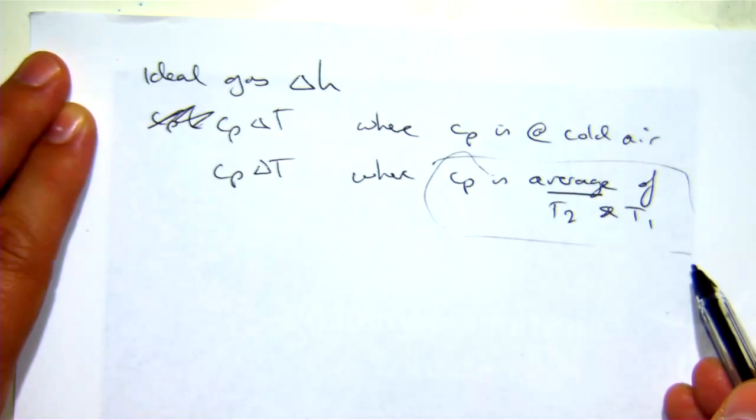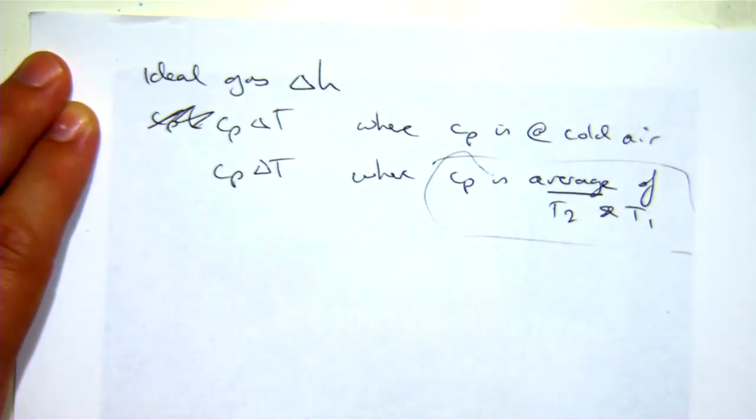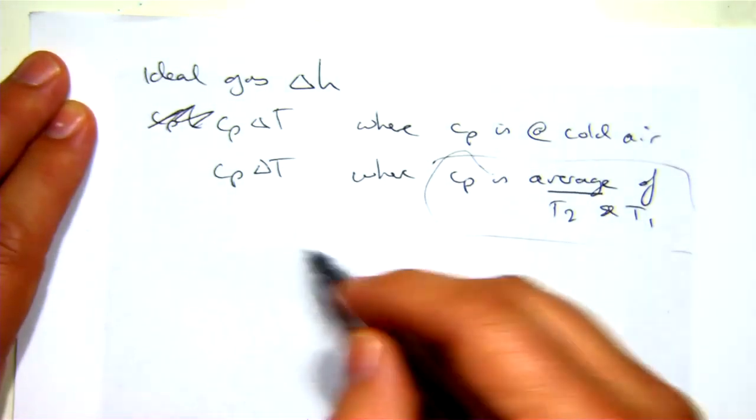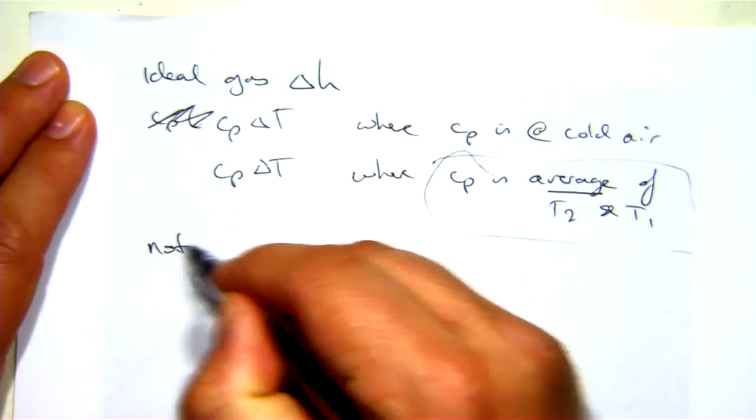So that becomes an iterative process that is a little bit tricky to do. But usually your first guess, if you know you're dealing with a gas turbine, you know your output's going to be of order 800, 900, 1,000 from the compressor, you have a good idea, once you've done a few of the questions, approximately how big this number is, and your average will be pretty close.